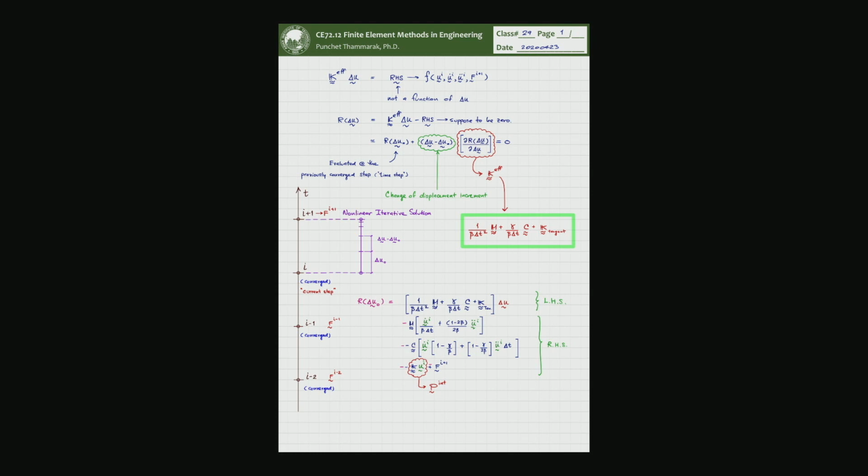Many times the calculation or analysis still continues even though some of the material is approaching the ultimate state. So some part of the beam might be crushing. It reached the crushing strain. Concrete might be going flat, or steel might be yielding. But if the other parts are still intact and carry the load from one place to another, then the analysis might still continue.